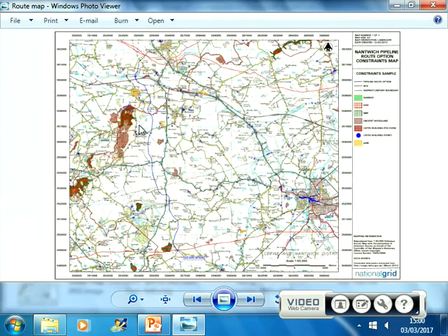Right. In terms of calculating the proximity distance, what you need really is the design factor. You get the proximity distances by looking at the diameter and the maximum pressure, and then you use the proximity. Have you got, from the code, the other chart, which has the diameter and the operating pressure? That's how you calculate the proximity distance. There's an equation on that graph which tells you how to calculate. That's the one according to the code, the proximity distance which is recommended by the code.